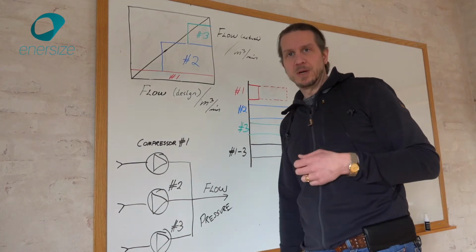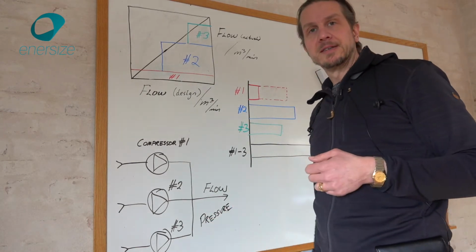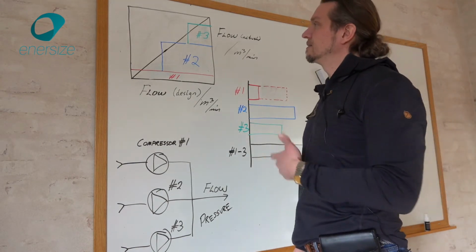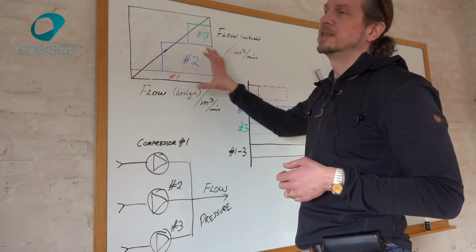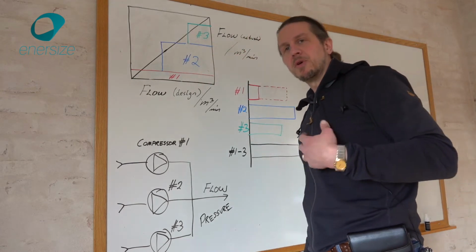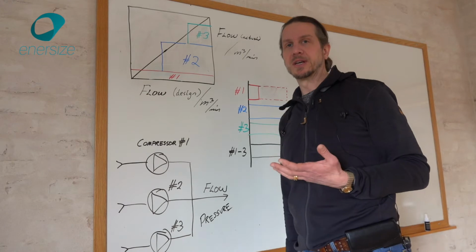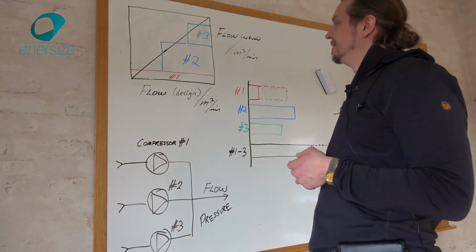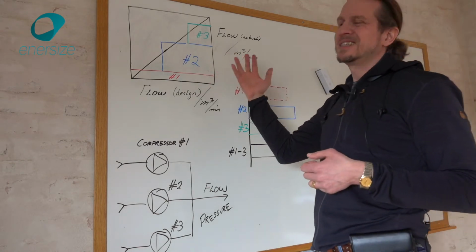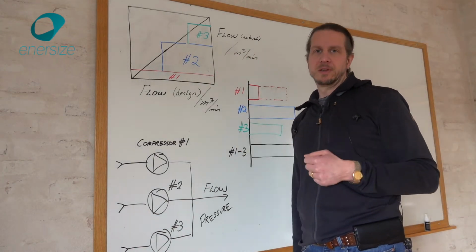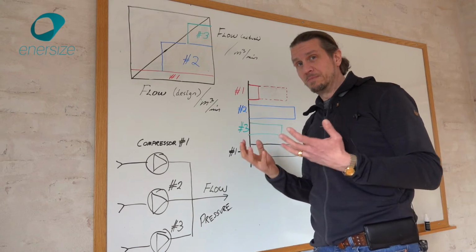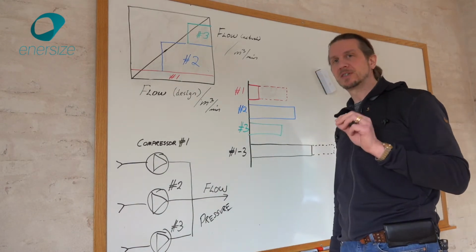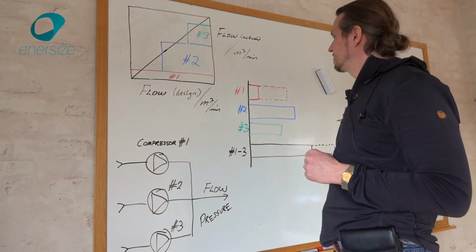So what happens then? Well, basically the pressure starts to fluctuate, the compressors don't work all right together. It can even be in other situations, even if you manage to design this in a good way, appropriate for the factory, still the compressors don't run because they are not cooperating with each other in a good way. And furthermore, this doesn't give you any quantitative information about how bad is the system, what is the inefficiency. And that's what we want, right? We want to see how to improve the efficiency of the system.